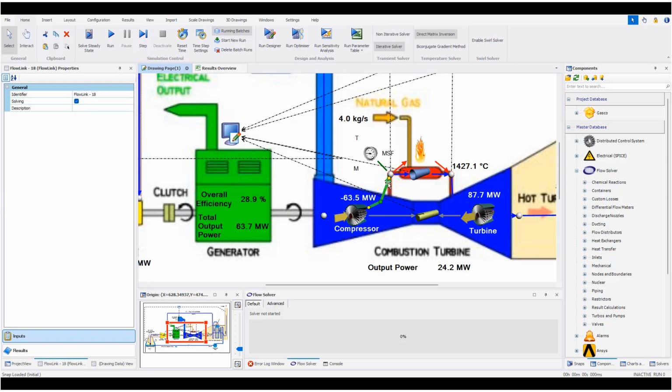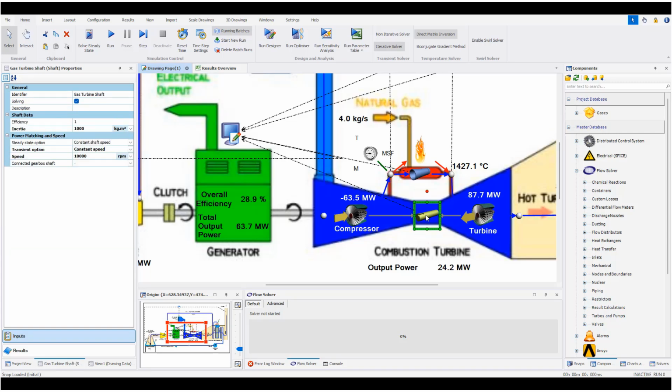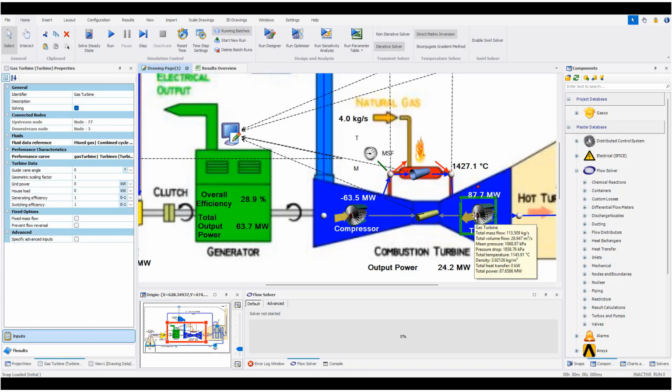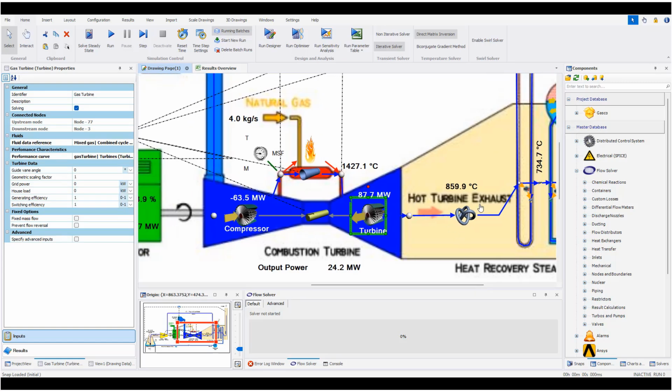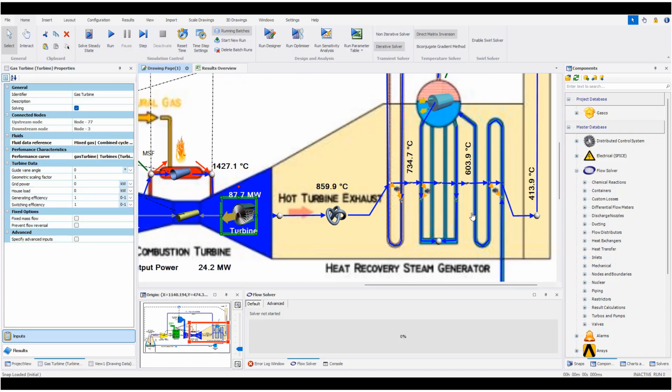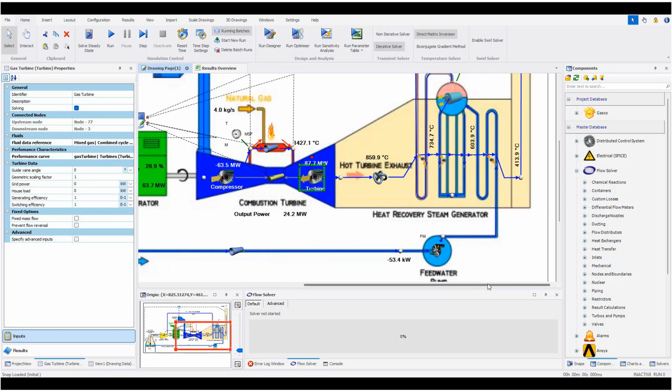and then after that going toward this flame section for the combustion, and going back to the turbine. The turbine and the compressor are connected with the shaft, and after that we have the hot exhaust gas that will be sent to the boiler, or we call it here heat recovery for steam generation.